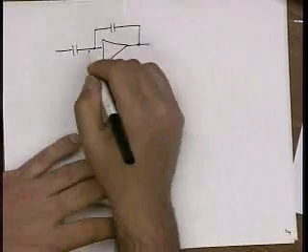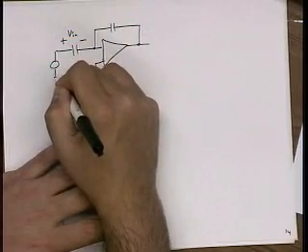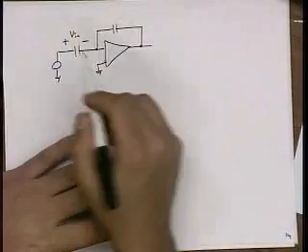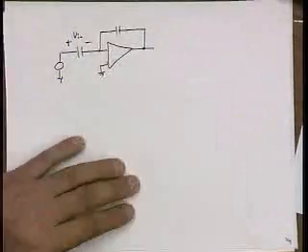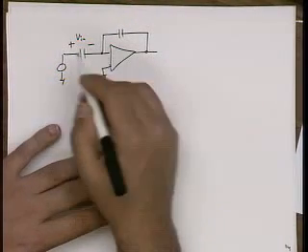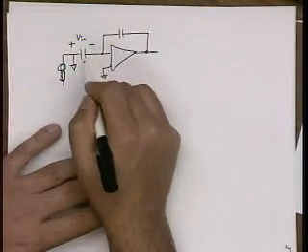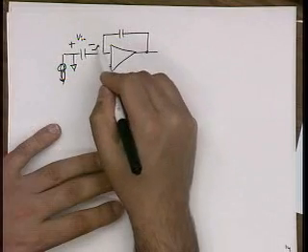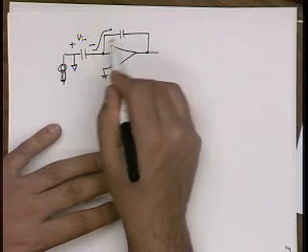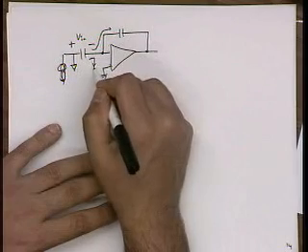So in cycle 1, remember I charge this up with V in, and I disconnect the amplifier, discharge this capacitor, and then in cycle 2, I present this circuit to my amplifier, which immediately causes a step. In cycle 2, I ground the input, and now I have a full V in across this capacitor, and this charge rushes over here and produces charge sharing between these capacitors, and I immediately get a step at my input.